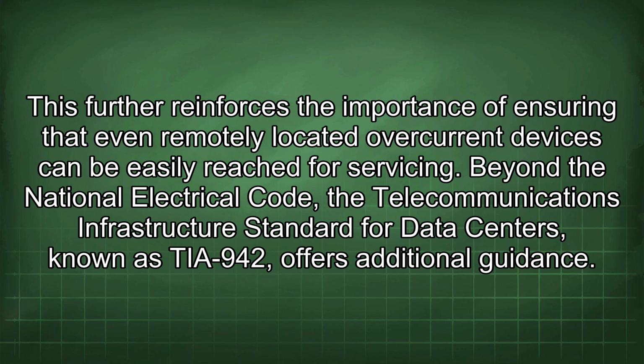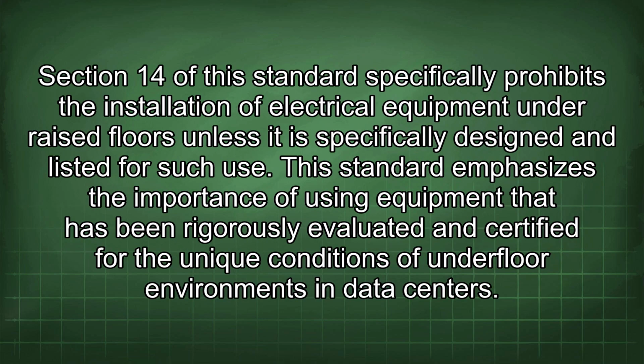Beyond the National Electrical Code, the Telecommunications Infrastructure Standard for Data Centers, known as TIA-942, offers additional guidance. Section 14 of the standard specifically prohibits the installation of electrical equipment under raised floors unless it is specifically designed and listed for such use. This standard emphasizes the importance of using equipment that has been rigorously evaluated and certified for the unique conditions of underfloor environments in data centers.